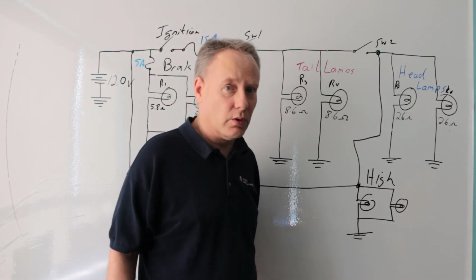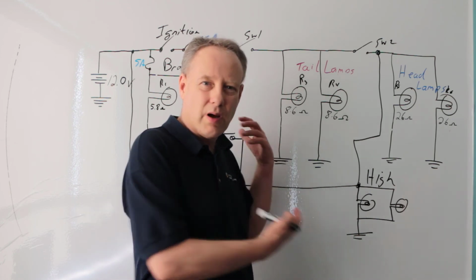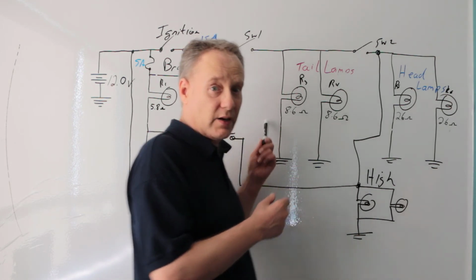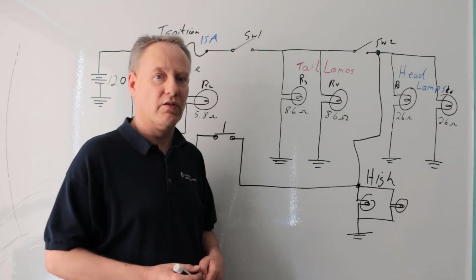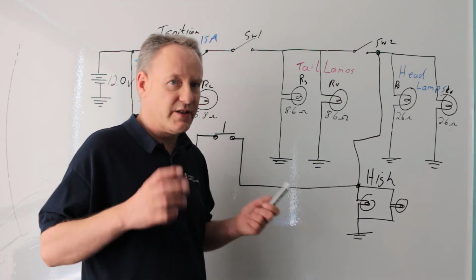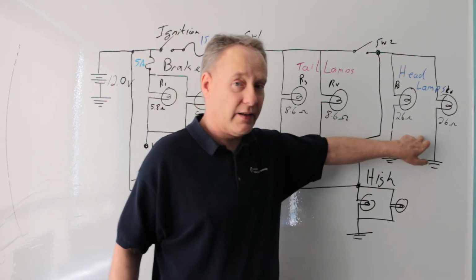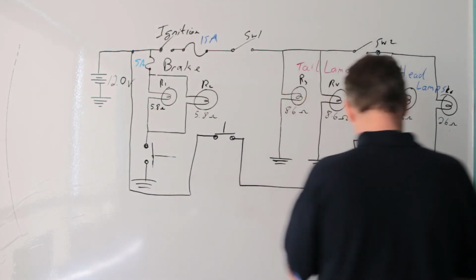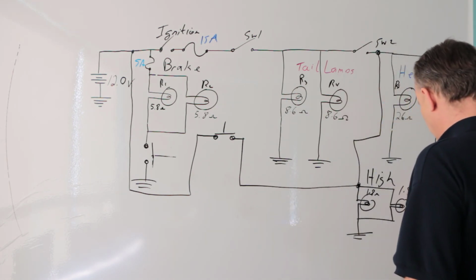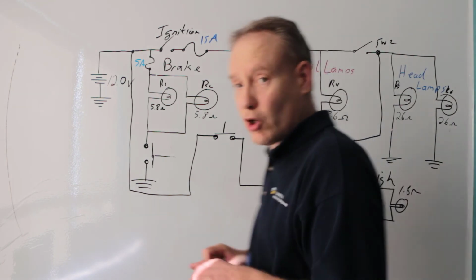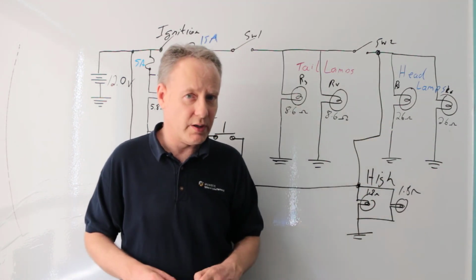So that's really cool. Now, before I let you go, I'm going to ask you, what is the problem here? We just created a problem that now we have to go back to the drawing board and solve. And the hint to this is high beams are even brighter than headlamps. Watch this. 1.8 ohms. Now they're lower resistance than these, so therefore they're going to draw more current. Goodbye!